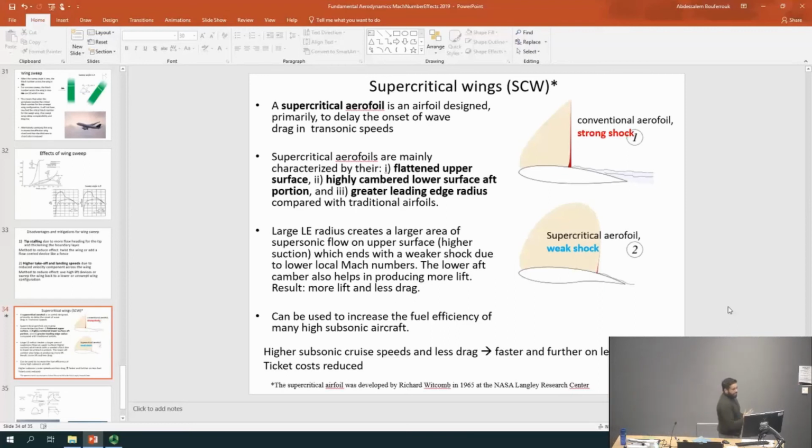Nowadays, I can tell you that a lot of aircraft that fly in high subsonic to transonic Mach numbers most likely have supercritical wings, because everyone realizes you can save a lot of fuel by having a supercritical wing. And I'm sure a lot of Airbus aircraft are already probably with supercritical sections, but obviously they don't tell anyone, neither do the Boeings and the other aircraft manufacturers. But surely when you see all these benefits that allow you to fly faster, getting your lift and less drag, clearly everyone wants to do that. So I'm pretty sure that a lot of aircraft these days use supercritical airfoils.